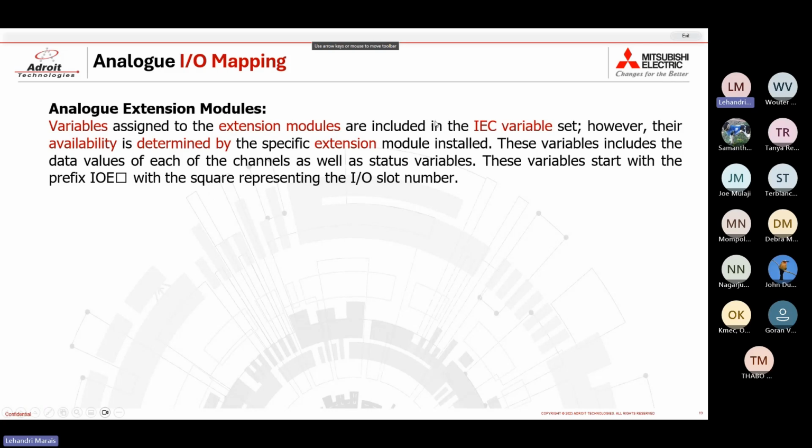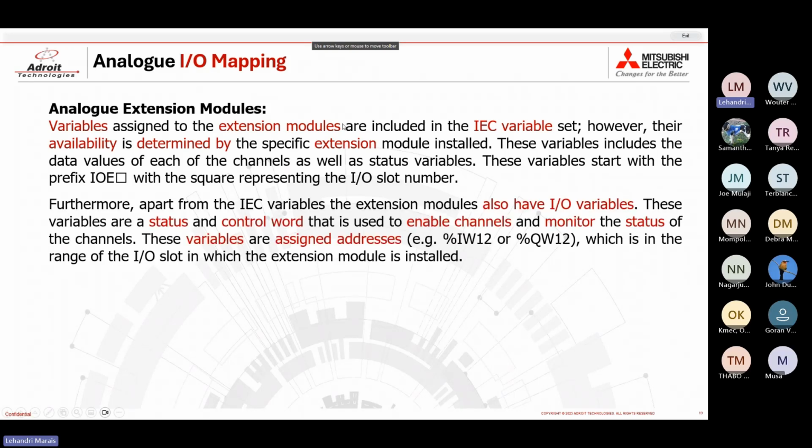Now, these variables of the extension module that form part of the IEC variables, they hold the channel data as well as some status data or variables as well. However, there's a second category of variables for your extension modules, which are your IO variables. So the difference between these and your IEC variables for the extension modules is these have physical addresses assigned to them, and the variables that you have for the IO variables are a status word and control word, which are used to enable your channels and monitor the status of your channels.